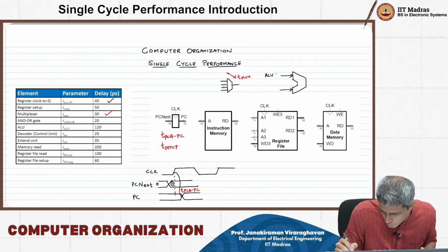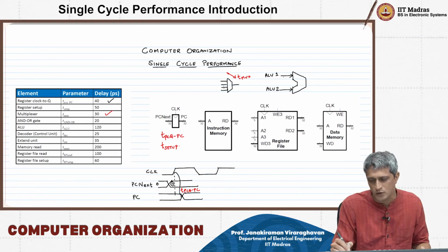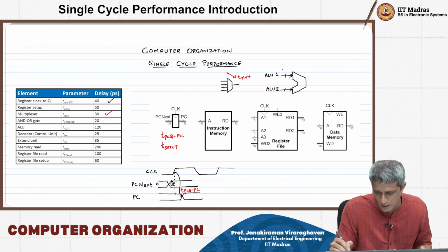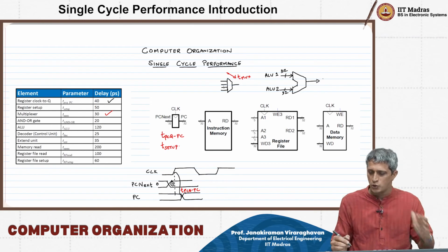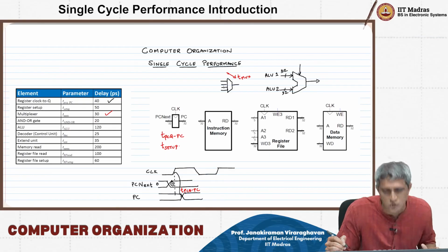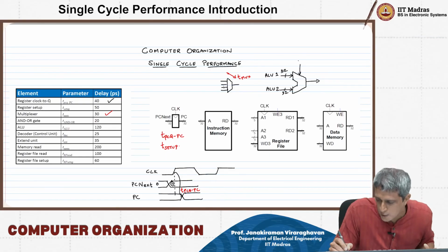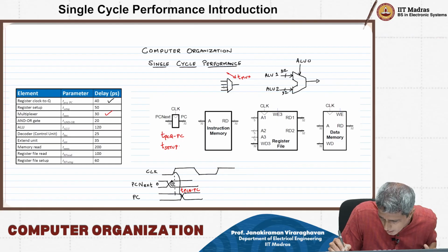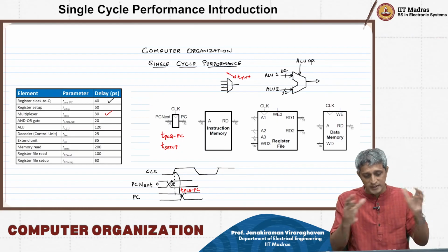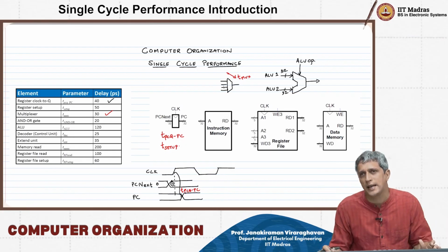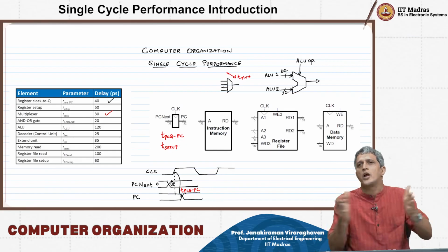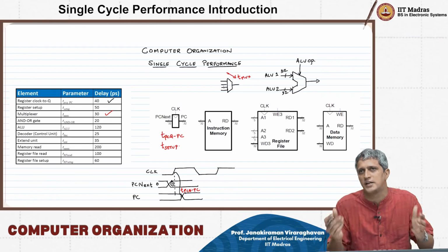Some ALU1, ALU2, and each of these is a 32-bit number, right, 32-bit bus, and you get an output of this. Now what operation you are going to do is going to be selected by some other ALU operation, if you remember, right, and the ALU time is going to be characterized by the longest operation that it can do, right.